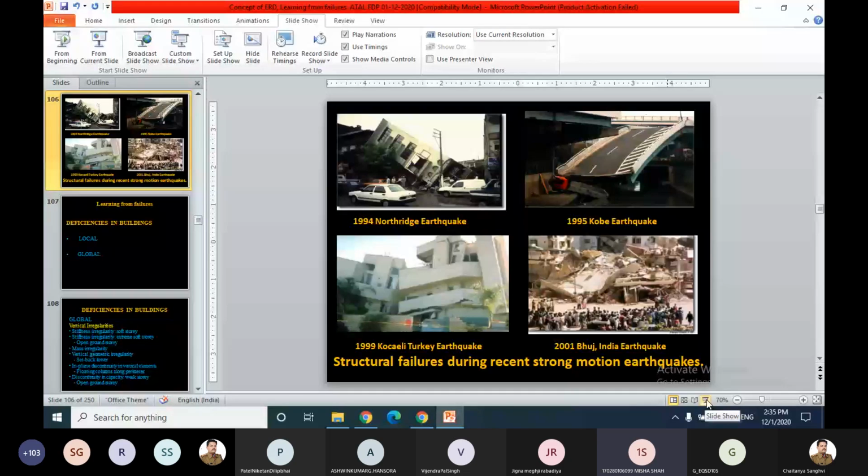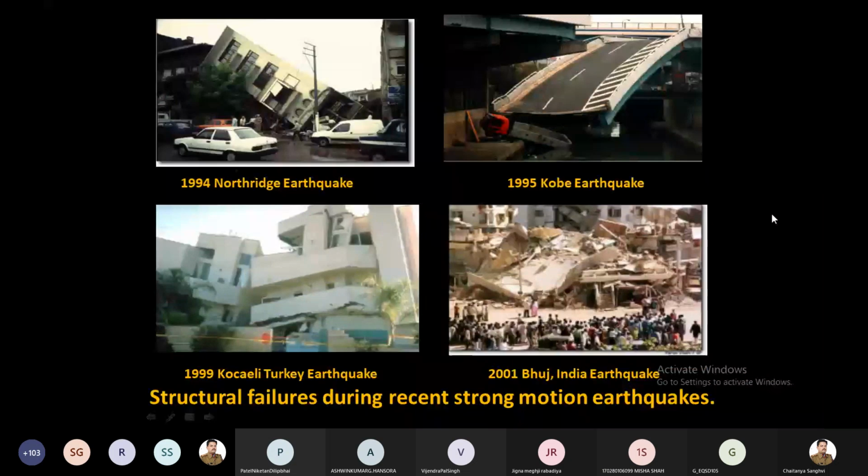Okay. So before lunch, we were discussing that we talk about earthquake resistant design. We are not going for earthquake proof design. The difference between earthquake resistant design and earthquake proof design is that in earthquake proof design, we are not allowing any damage. Your structure will remain within elastic range, and when the earthquake completes, your structure will come back to its original position without any damage.